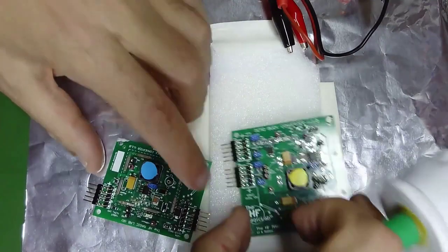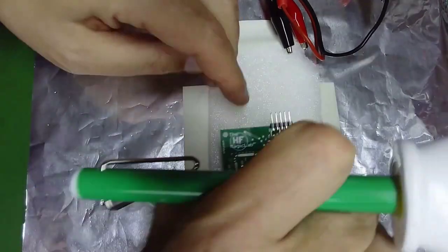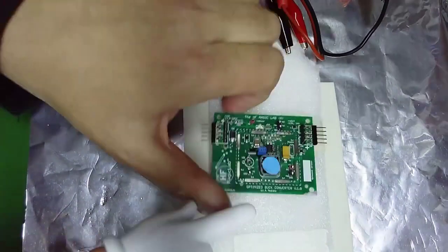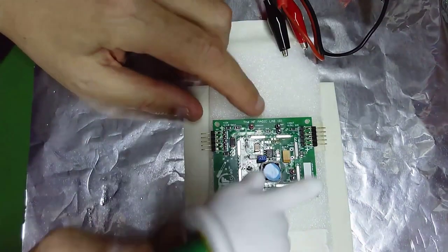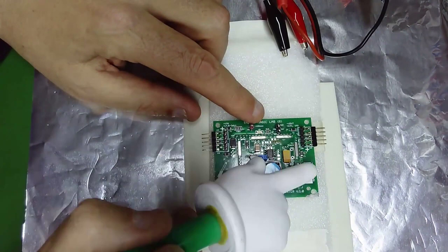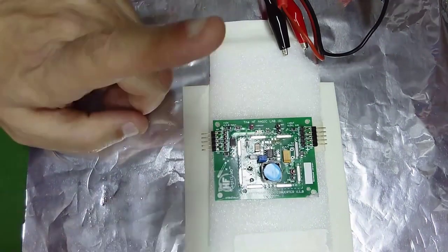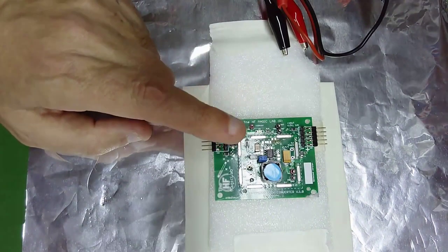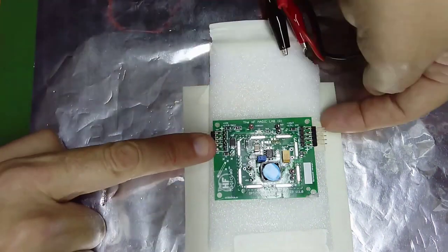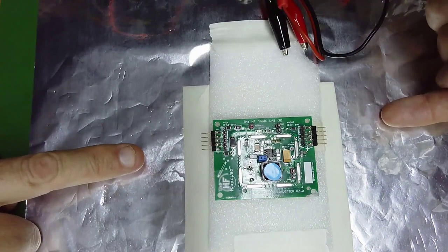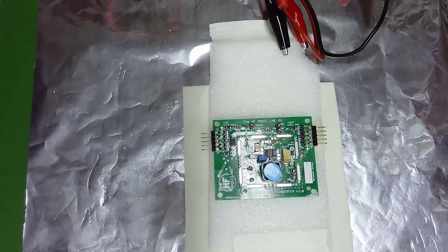Another strategy is to do this. It's the same circuit, but what I am doing is to put the input voltage here and the output voltage here. So they are in separated areas. This can have problems in radiated emissions, because with the cables here and here, you can easily create a dipole. But considering all the risk and your system, where the connectors go, you can solve many problems. But you know that sometimes solving conducted emissions, you destroy radiated emissions.